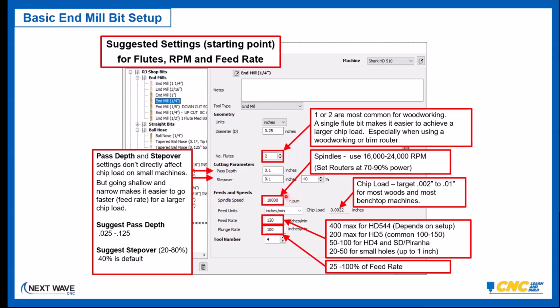When you increase your spindle speed, you'll also, I take that back. When you increase your spindle speed, you'll actually decrease the chip load. So by slowing down the spindle speed, you take a bigger bite. Now this is where it gets complicated because feed rate also affects it. The faster you feed it, the bigger the chip load. The slower you feed it, the smaller the chip load. So the 3 numbers that affect chip load are the number of flutes, the spindle speed, and the feed rate. Those are the only 3 things that affect the thickness of the chip load.